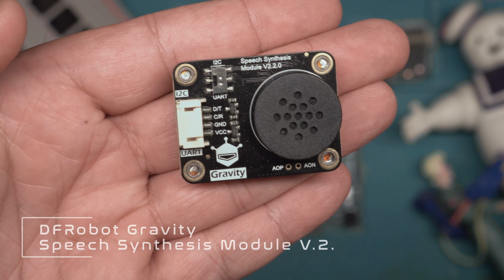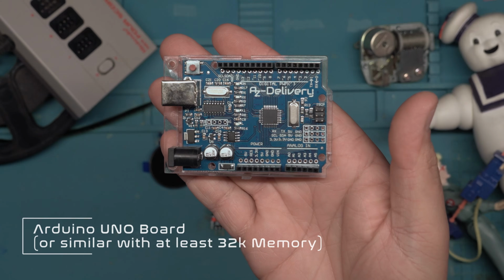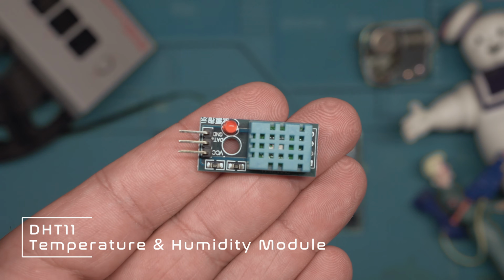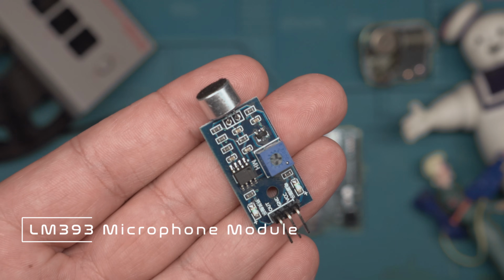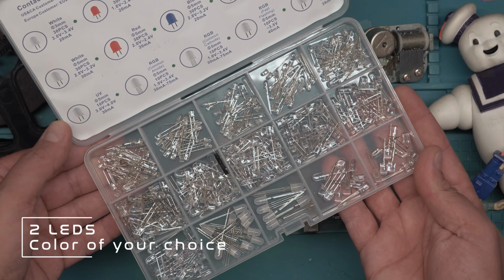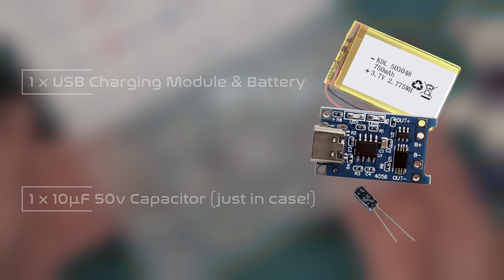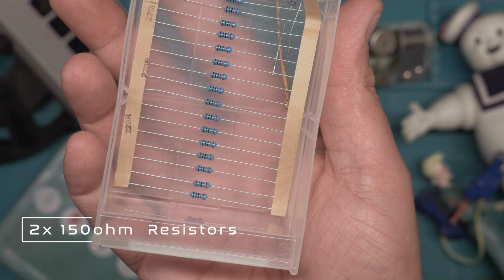The heart, piece and voice of the Spirit Chat is the DFRobot Gravity Speech Synthesis module, version 2.2.0. I use an Arduino UNO board for this build. Be aware that the code takes up almost the entire 32 kilobytes of flash memory. A DHT11 that measures temperature and humidity, this LM393 microphone module with adjustable sensitivity control, a GC9A01 round TFT display, and 2 LEDs in the color of your choice. A 750 mAh LiPo battery paired with a USB charging module and a 10 microfarad 50 volt electrolytic capacitor. Also a piezo buzzer, a micro switch, 1 toggle switch and 2 150 ohm resistors for the LEDs.